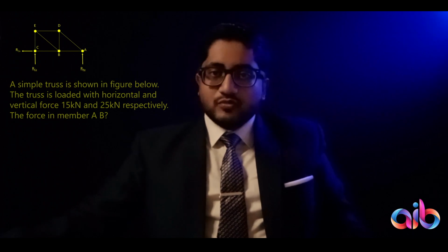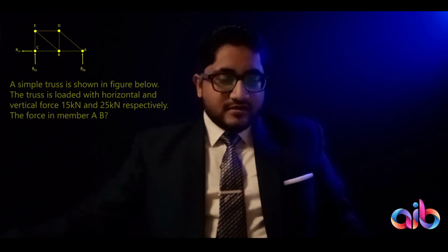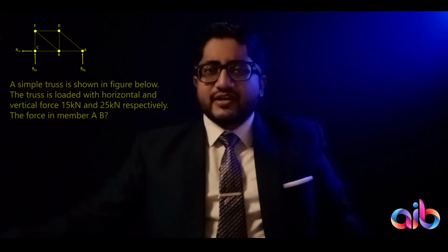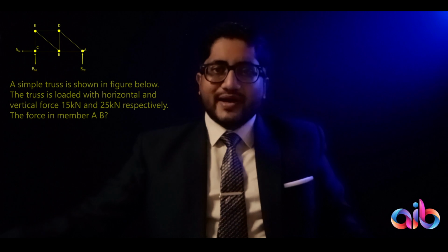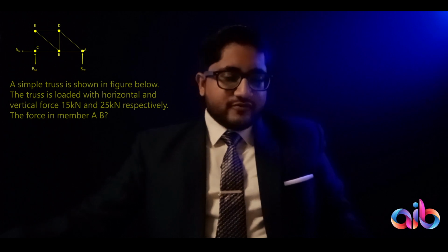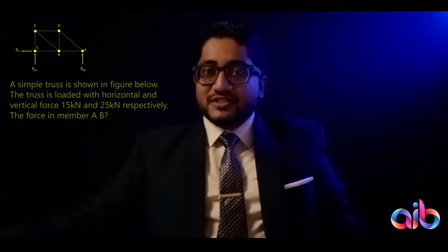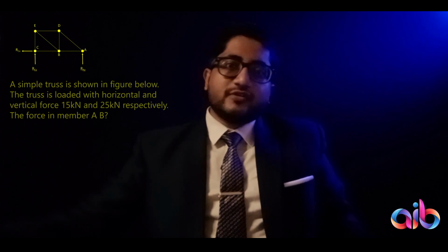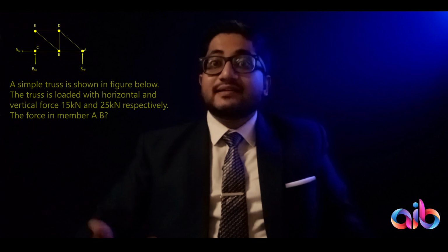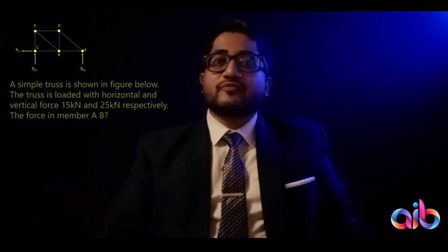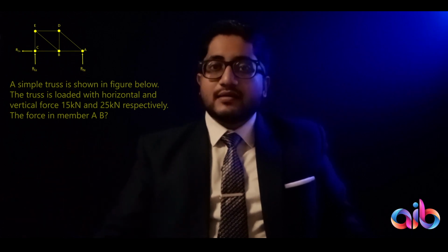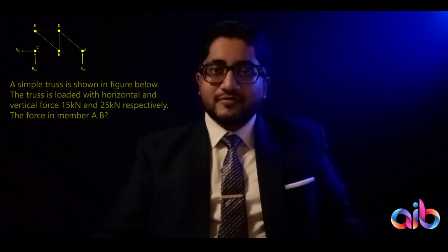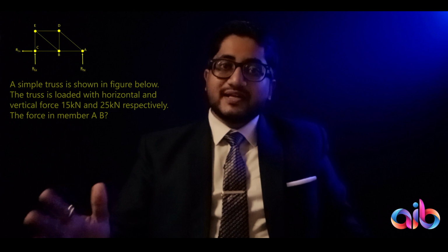So let's move on to the solution now. First of all, straight away use the law of statics and find out the forces in the x direction and the y direction. So the forces in the y direction add up to be 0, because the truss by itself does not fly off into space. So it means the resultant of all the summation of forces in the vertical direction is nil, because it is still there, it's statically there, it's not moving by itself. So there is no resultant force.